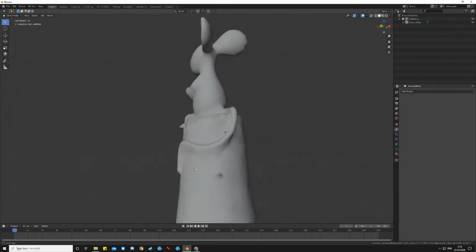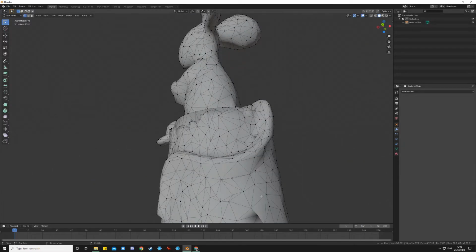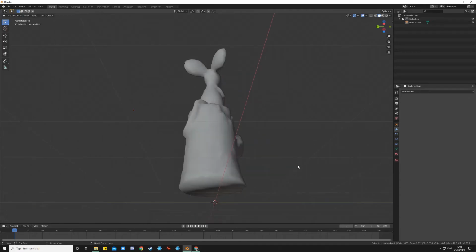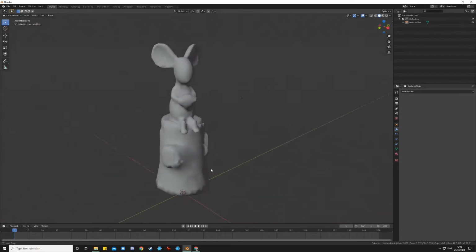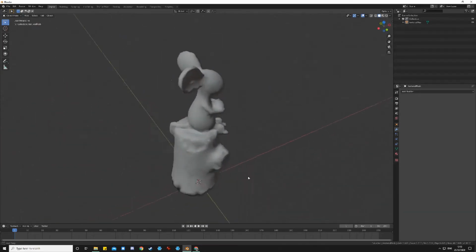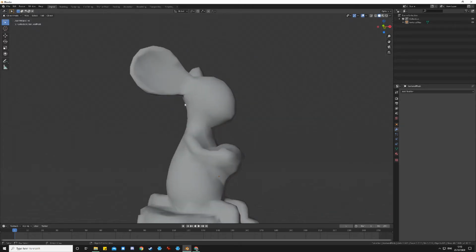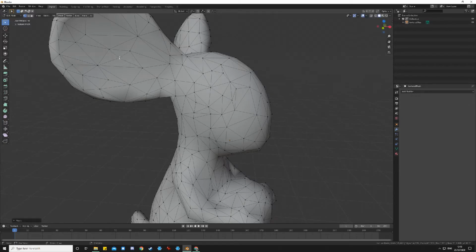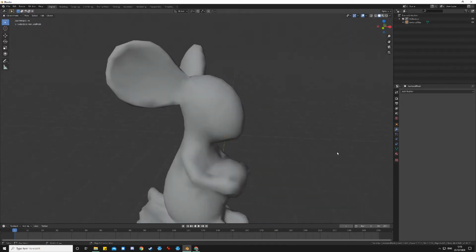And that actually helps me see any weird geometry in there. For example, I didn't notice that, but now because the smooth shader has highlighted it to me, I can see any problems like that. And that's where I go between object mode and edit mode. There you are. I didn't see that either. Straighten that out. Looks nicer.